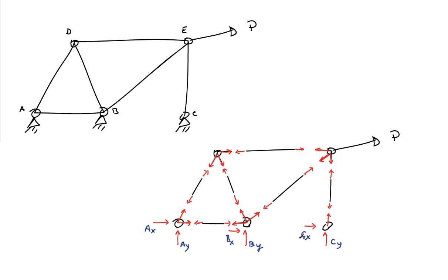And now I also have my bar forces. So over here I'm going to call this F1, and these are equal and opposite right here. And these two guys up here are also F1, just simply by action equals reaction and taking advantage of the fact that this bar here is a two-force member. Okay, so that really reduces the number of unknowns. Originally in that picture it looked like there was 1, 2, 3, 4 unknowns, but really they're just one unknown.